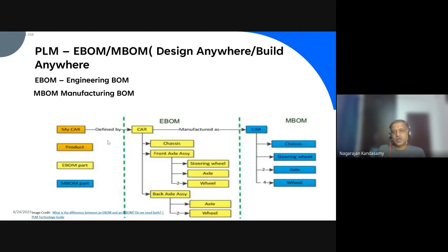As a design engineer, you would be doing a top to bottom assembly or bottom to top, depending upon the product. So you'll be able to extract the engineering bill of material from your CAD model, as mentioned here on the left hand side. But the same bill of material cannot be used in a typical shop floor, because the arrangements are different. Beyond your product, there are consumables, tools, and fixtures required to manufacture the product, though they do not go along with the product.